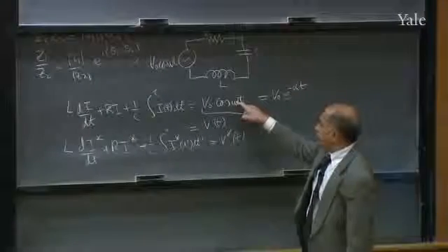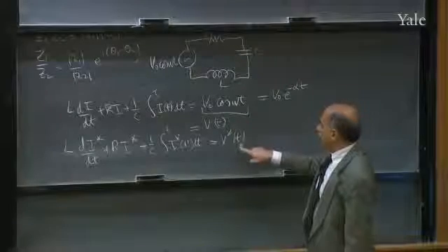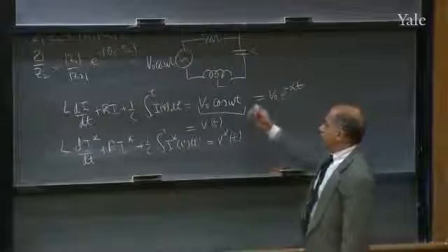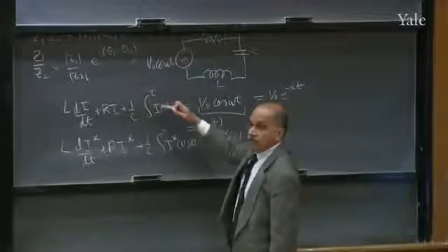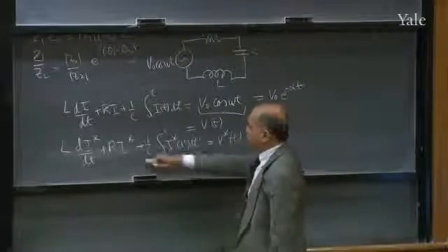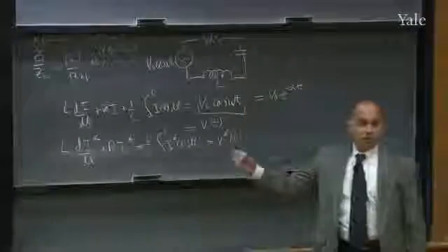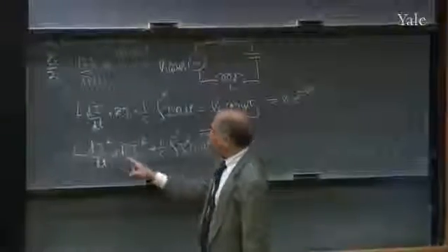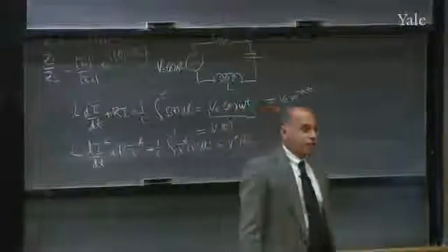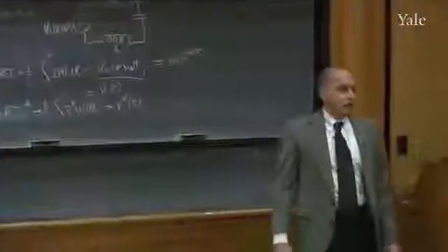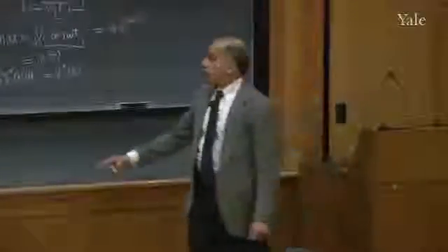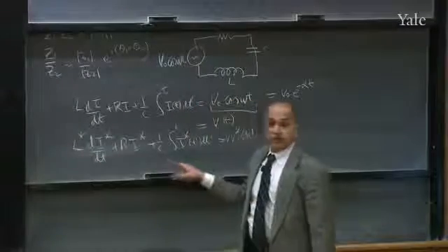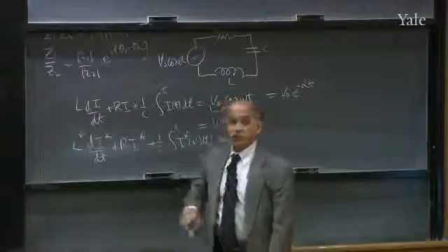So that solution for v of t implies a second equation. In other words, if the voltage v drives a current I, the conjugate of the voltage drives the conjugate of the current. That simply follows from the equation. It comes from the fact that when I conjugated it, L, R, and C are real. Do you understand that? Suppose L were imaginary or had an imaginary part, then I must also put a conjugate on L. Then I star obeys a different equation, because this had L in it, this had L star in it.